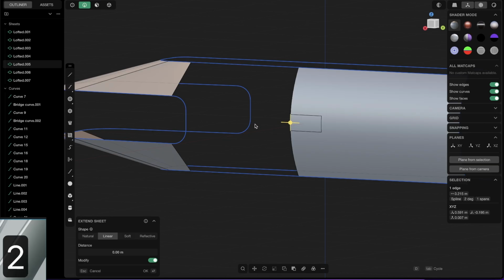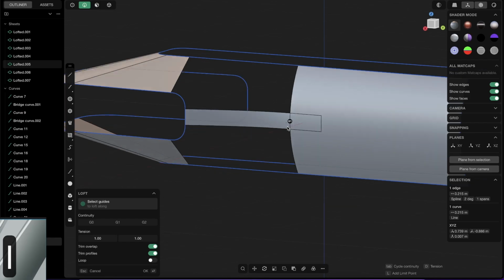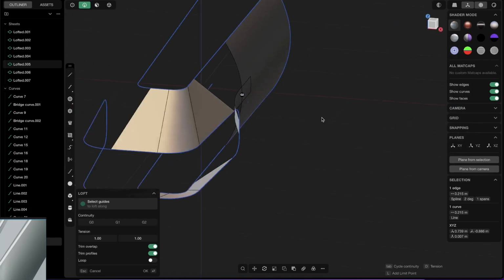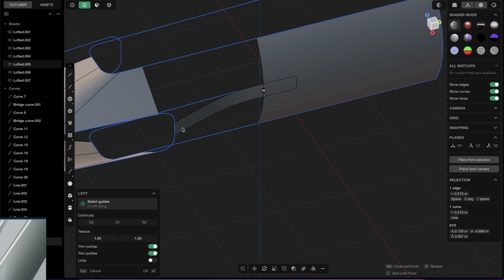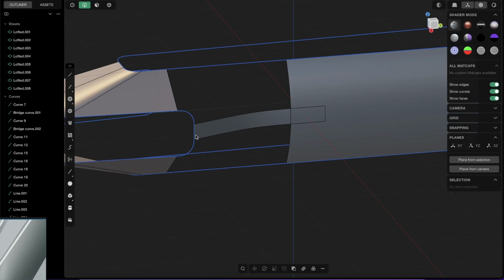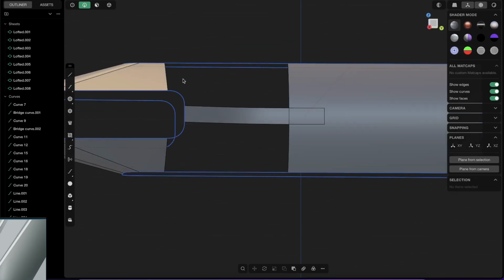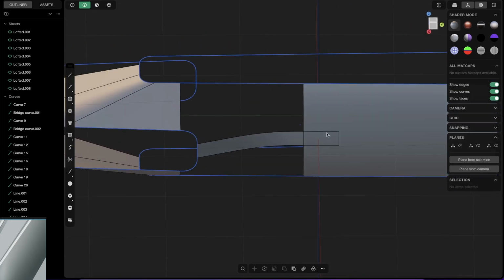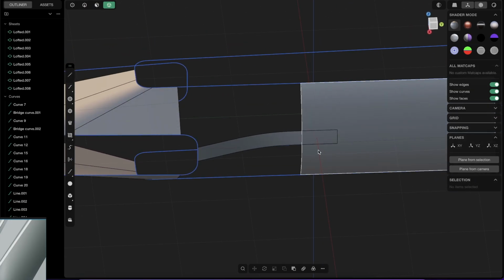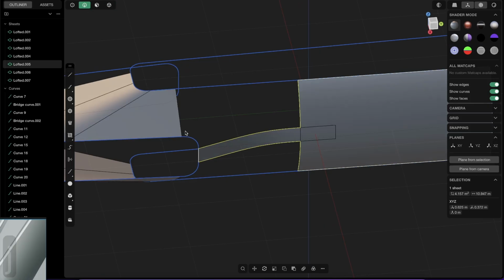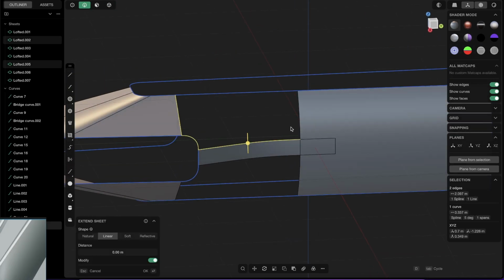And if you select this little edge here and this curve and press L for loft, you can give it here G2. And you see we already connect here in a nice and smooth way. And we did that because we had this big hole, but now we just have two much smaller holes, and now we can work with patch. But before that, go to object mode, select those two faces, press J to join them, go to edge mode again, and now let's select all of those surrounding edges and just patch it.